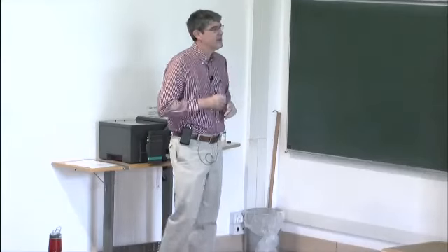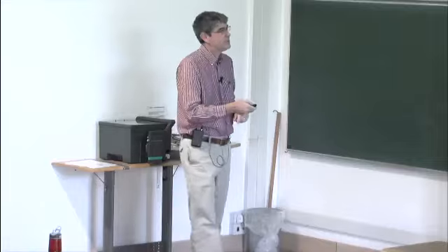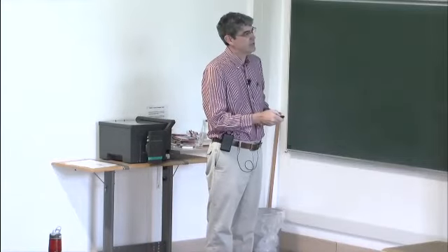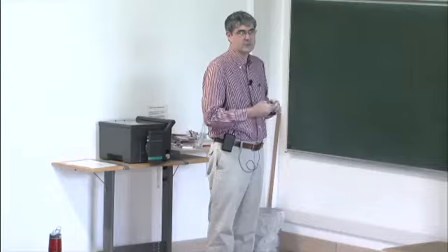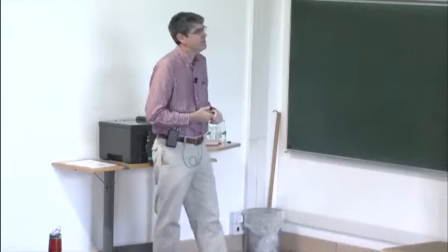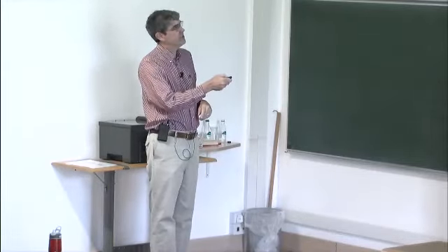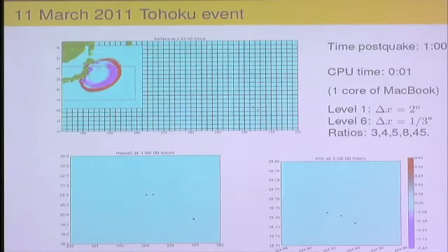So we've got a huge refinement between the coarsest and finest level. These are the ratios we go down by at each level, and going from level 5 to level 6, for example, is a factor of 45 refinement. So initially, we start with only 3 levels of refinement, this coarse one, and then there's a box here where I didn't draw the grid lines, where it's refined by a factor of 3, and then another box here where it's refined by an additional factor of 4.